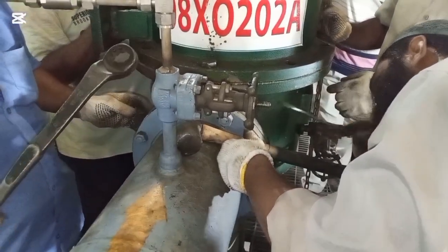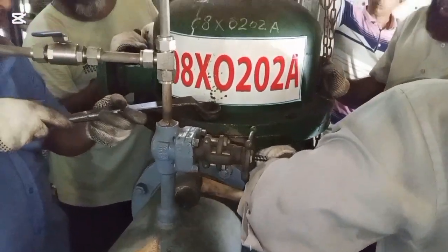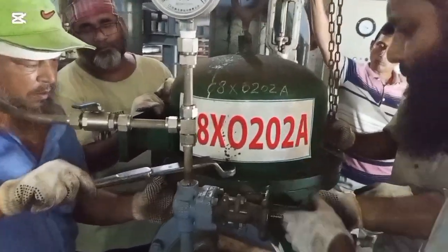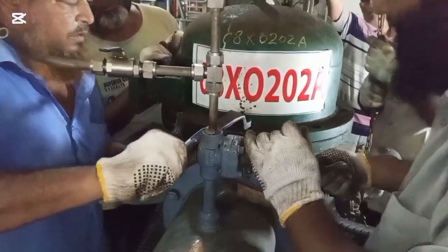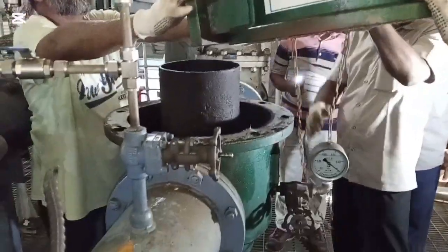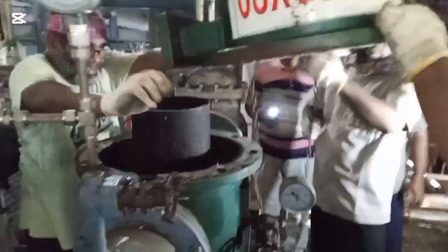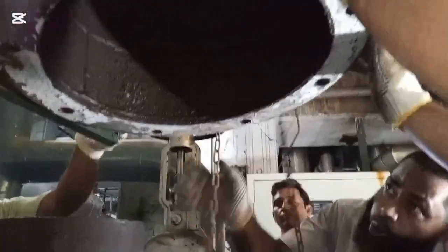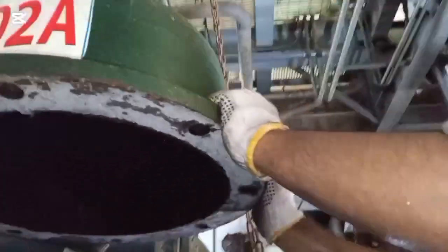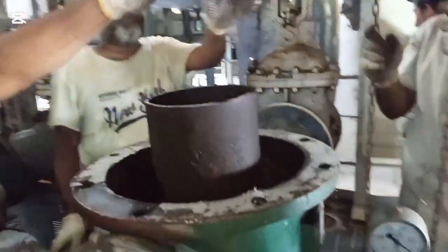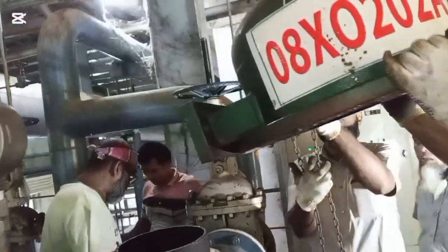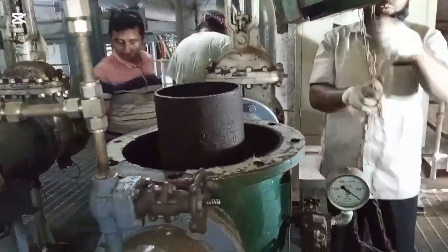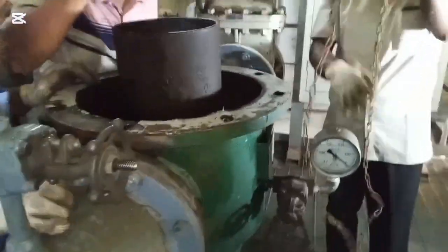The main function of the ejector is in the condensation system of the turbine. Simply, steam ejectors are used to create a vacuum within a system. This is done by injecting water or steam into the system at a high pressure and velocity, which causes the air or other gases inside to be expelled from the system at a high velocity as well.